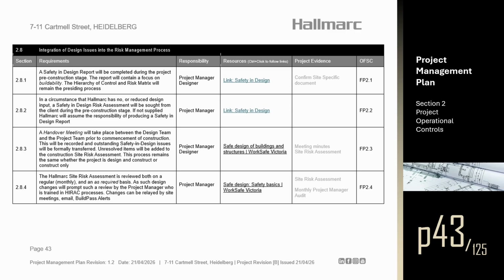Section 2.8.3. A handover meeting will take place between the design team and the project team prior to commencement of construction. This will be recorded and outstanding safety in design issues will be formally transferred. Unresolved items will be added to the construction site risk assessment. This process remains the same whether the project is design and construct or construct only. Section 2.8.4. The Hallmarc site risk assessment is reviewed both on a regular, monthly, and an as-required basis. As such, design changes will prompt such a review by the project manager who is trained in HIRAC processes. Changes can be relayed by site meetings, email, or BuildPass alerts.